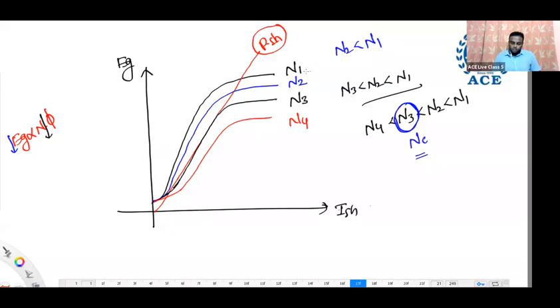So like that, whenever speed is reducing, EMF also reduces. At one of the speeds, that OCC will become tangent to the field resistance line. Wherever it becomes tangent, that speed we call the critical speed of the generator. So this is the critical speed.